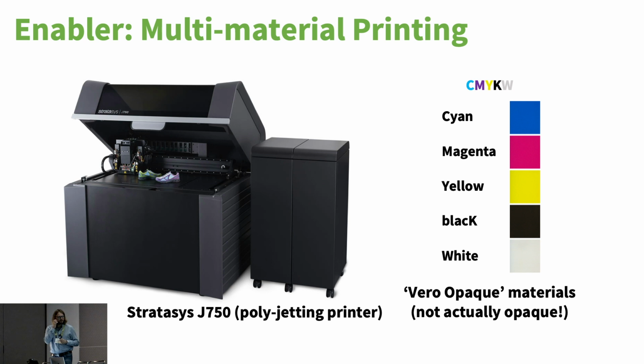But there are some problems. One thing that is inherent to this 3D printing technology is the translucency of the printing materials, because they are sensitive to UV light. They harden by being exposed to UV light, so the UV light needs to be able to enter the material. They just have to be translucent in the first place for this technology to work.